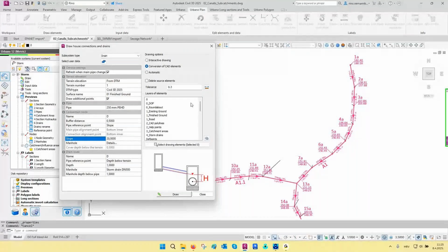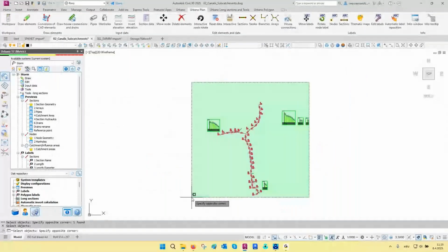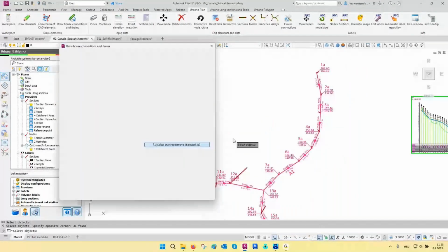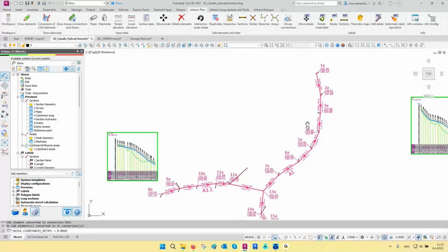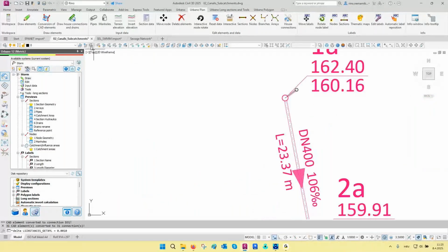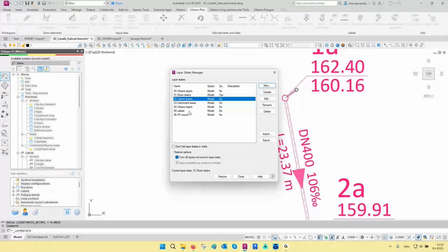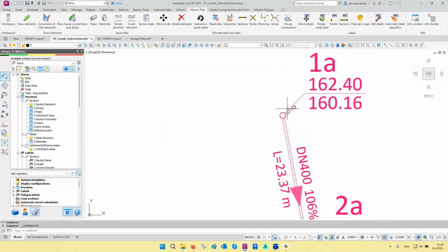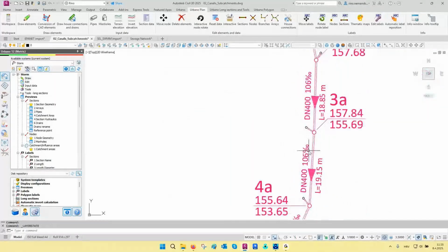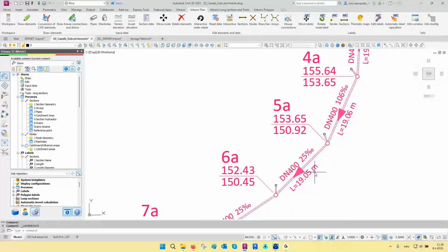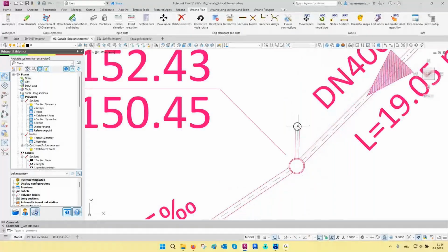Again, I will use this layer filtering option to select just the layers on the selected layer, like this. And now when we click Draw, all these plain AutoCAD lines will be converted to Urbano drains. So let's turn off now this layer containing the original lines, and you can see that we successfully drew 31 drains, and each drain has the manhole defined in the starting node.